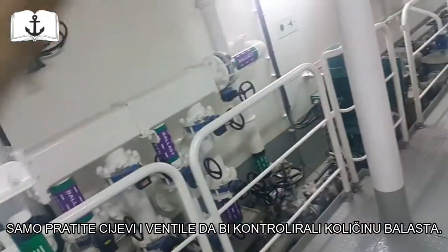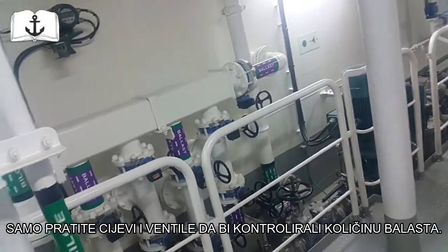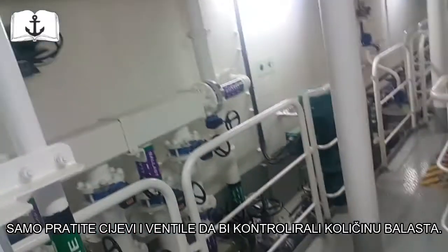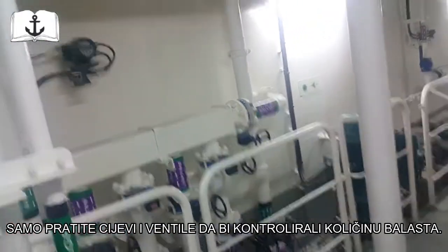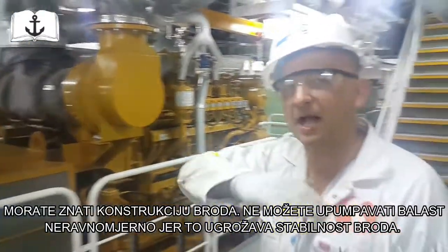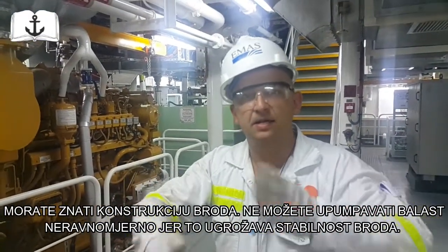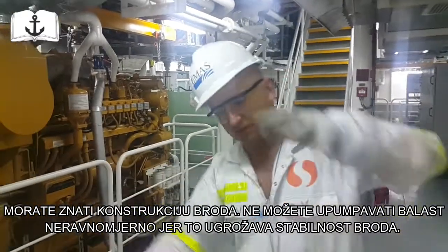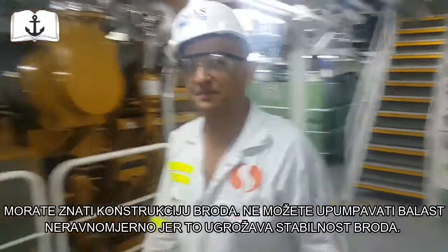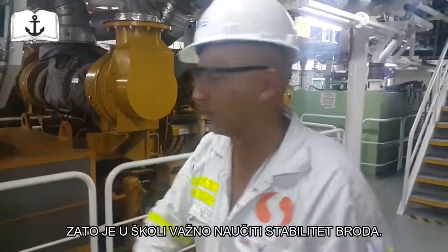So you just need to follow the line and open the valves which you want to open. And you need to know what you're doing, otherwise you capsize the ship. So you need to understand how the system is working. You have to know the structure of the ship, that we can say it's a big bowl with chambers. You can't put all the ballast on one side. So a good idea would be to take a drawing and see what you're doing.